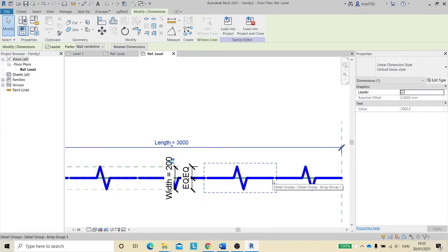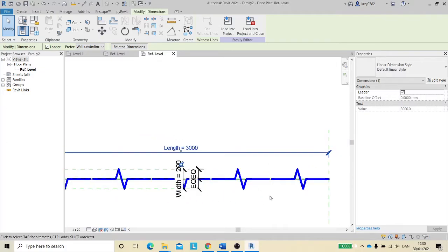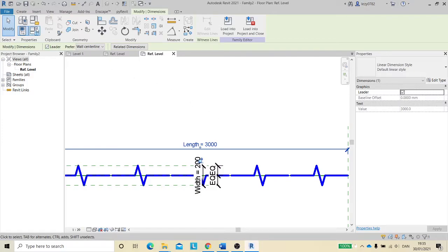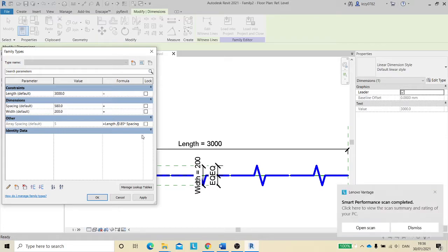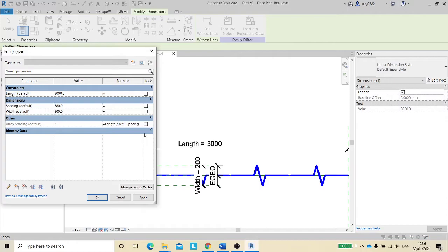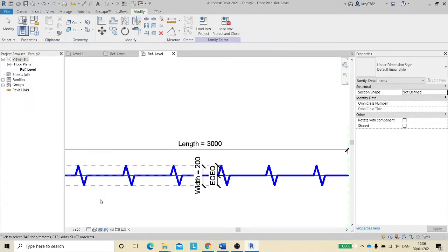This is actually a glitch from the array when trying to fit another one, but I'll show you the trick how to do that a little bit better. So just type 0.85, so that will be multiplied, it will be 85% of our spacing, and just place some parentheses over and apply. You can see that looks much better now.